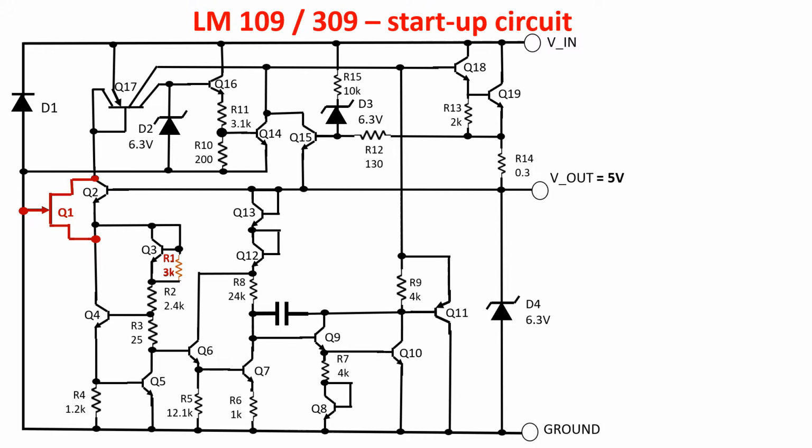When we apply the raw voltage V into the circuit, the drain of the FET goes high and Q1 turns on, making current flow in Q4. Because of the working of the FET, the maximum current is just when the voltage between gate and source is zero, so a current biases Q4, turning it on. A voltage rises on R4 and when it reaches 0.7 volts, Q5 turns on. A current I5 is created and this current initially flows through R1, turning on Q3 and Q2.